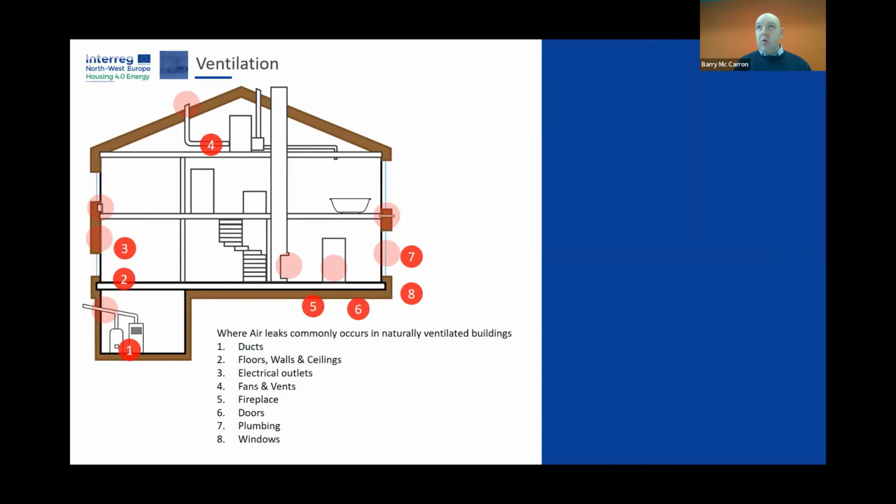It depends on how exposed your house is. Is it on top of a hill, exposed, or is it down in a hollow with loads of trees around it? A lot of variable factors will affect how well your house is insulated. One of the things that's commonly said with these MVHR systems is you might get something in the region of 10 to 14 complete air changes of all the air in your house in one day, whereas if your house is naturally ventilated, you might be lucky to get 3, depending again on a host of variables.